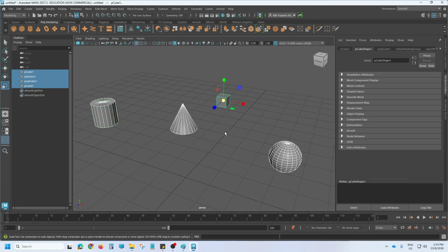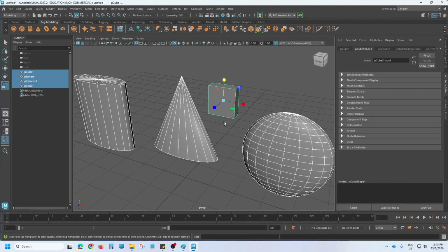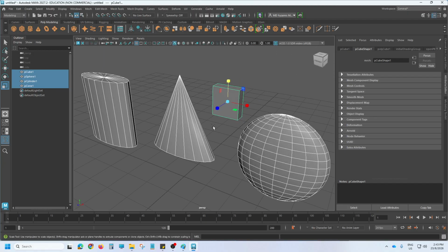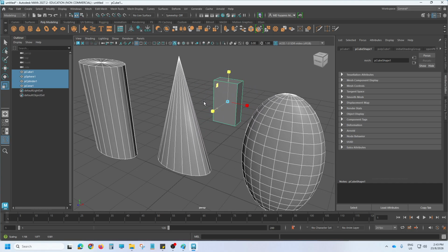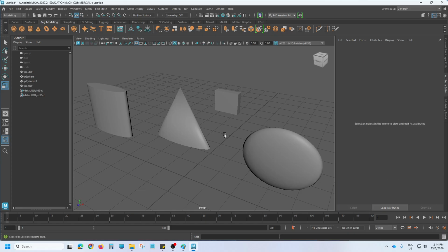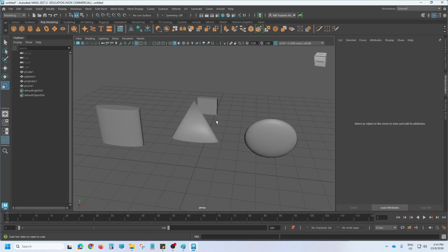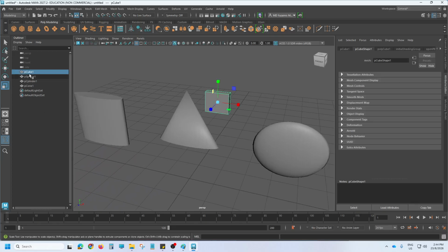For a non-uniform scale, you just have to push or pull one axis, like let's say X. So this allows me to stretch the model along the axis. So this is Y. So now it's a bit flatter. So that's how this works. You can also do a two axis combination at the same time if you want. So that is basically the scale transformation here.